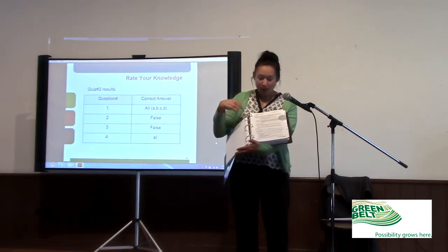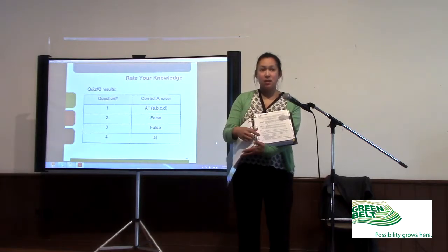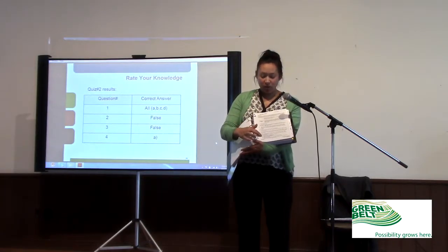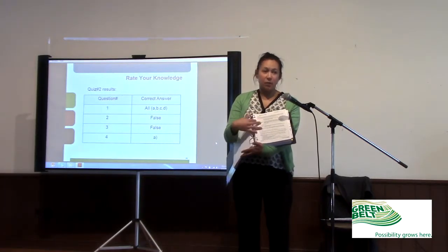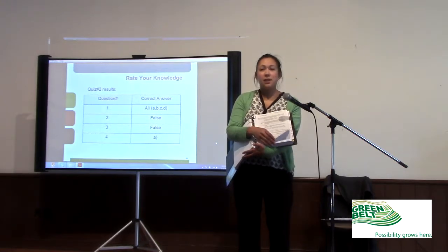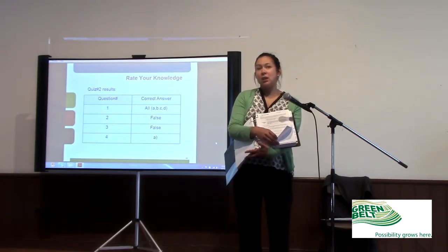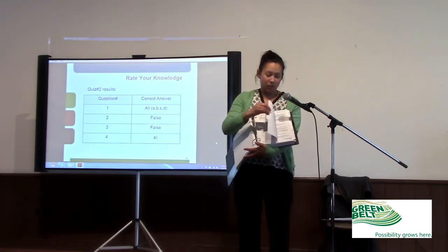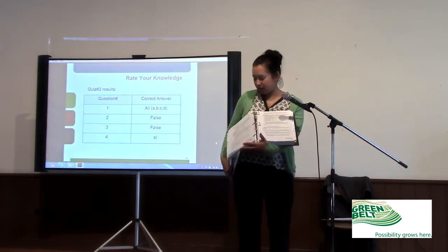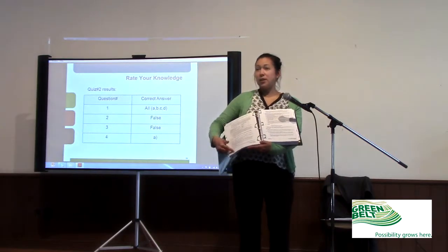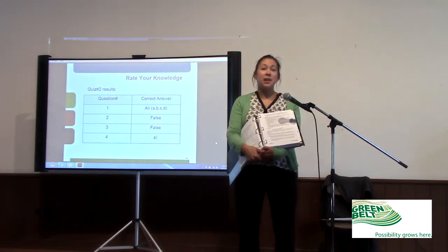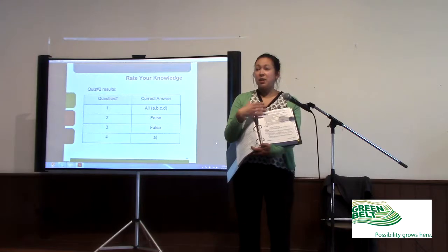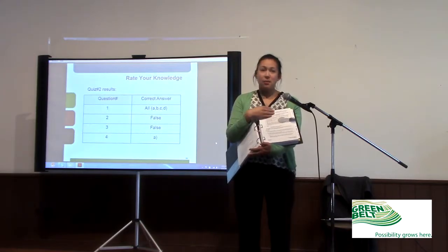So what it asks you to do is an assessment of your water source, and check for all the things that it lists on this first page in section 7. And then if you find some of these risk factors, you need to take some type of preventive or corrective action, and you would document that here on the next couple of pages in terms of what you've done about it. And again, testing, because if you think you've got a problem, it does say you should test in a lot of cases.